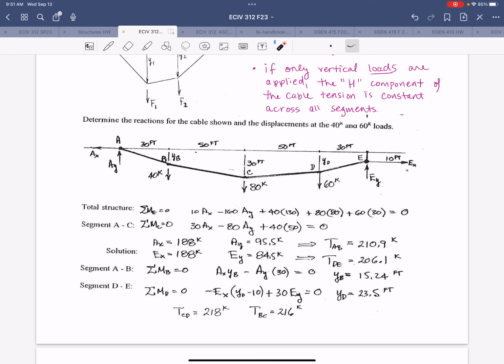So they may have done that analysis and determined that the load reversal would not be significant enough to counteract the effect of that gravity load from the weight of the roof. Or maybe this truss is not necessary for the lateral force resisting system, right? It's just part of the vertical load. So, yeah.